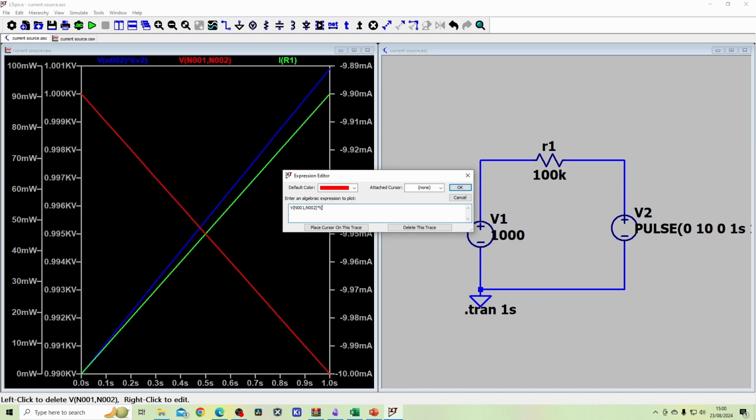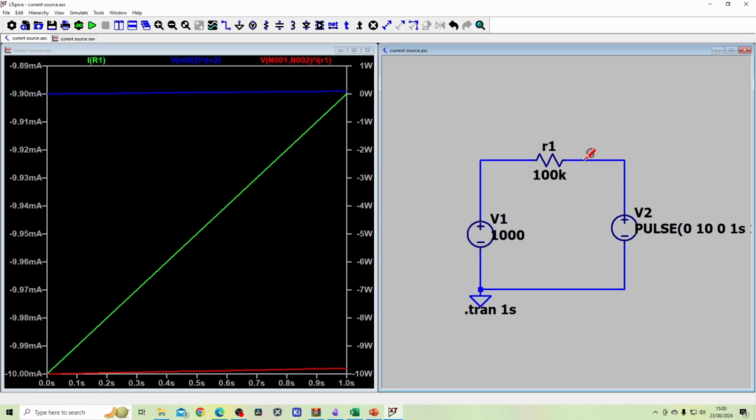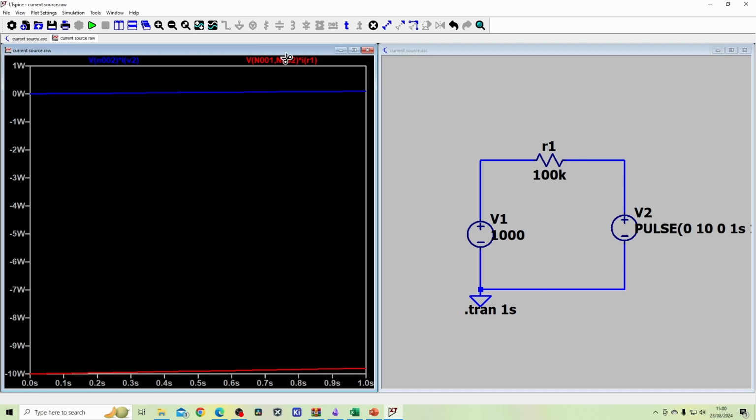In LTspice, we can also calculate the efficiency like we did in our question. So I'm going to basically get the power dissipation for the resistor as well and delete this current, and I can do this divided by this, and that would give me the efficiency for this circuit, which we calculated as being 0.1%. So this is the load and this is the dissipation series resistor. So this is the useful power and this is the wasted power.